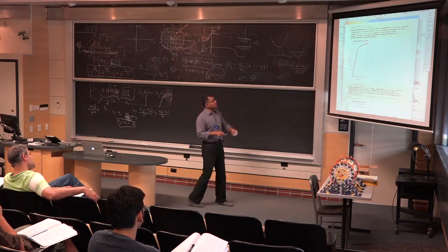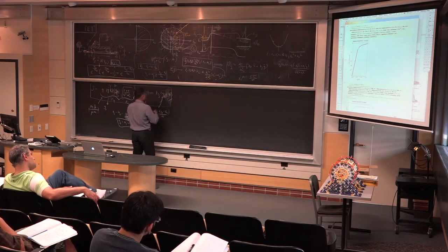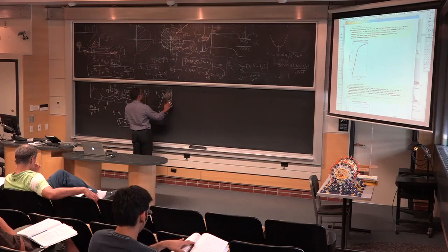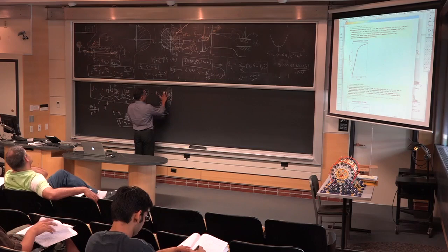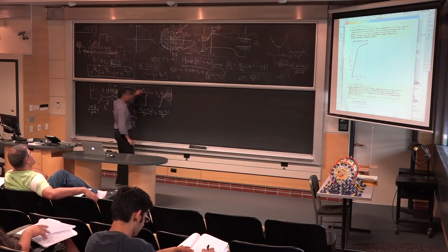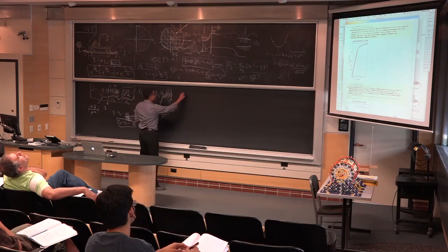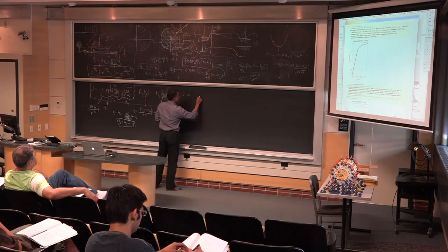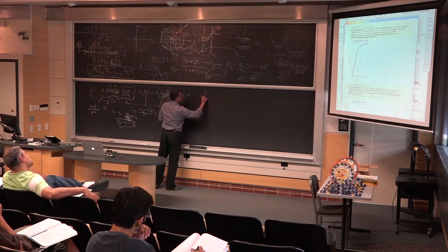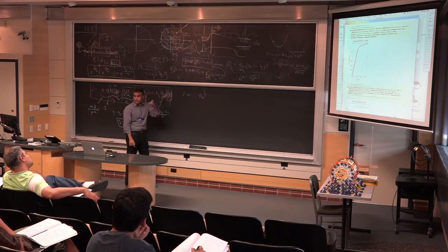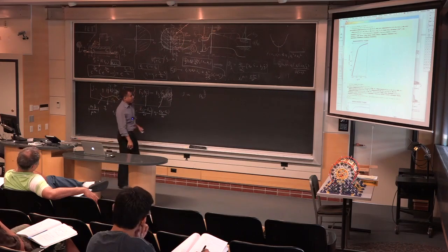Here it becomes polynomial, and what you can show is when VDS is very large, you get a Fermi-Dirac integral of a very large negative quantity, so you can forget this one. Only this one survives. And when that survives, the current becomes proportional to your gate voltage to the power, I think, 3/2. That's what it's going to become, proportional to gate voltage to about 3/2. From here, you can just do some algebra and find out this is how it's going to be.